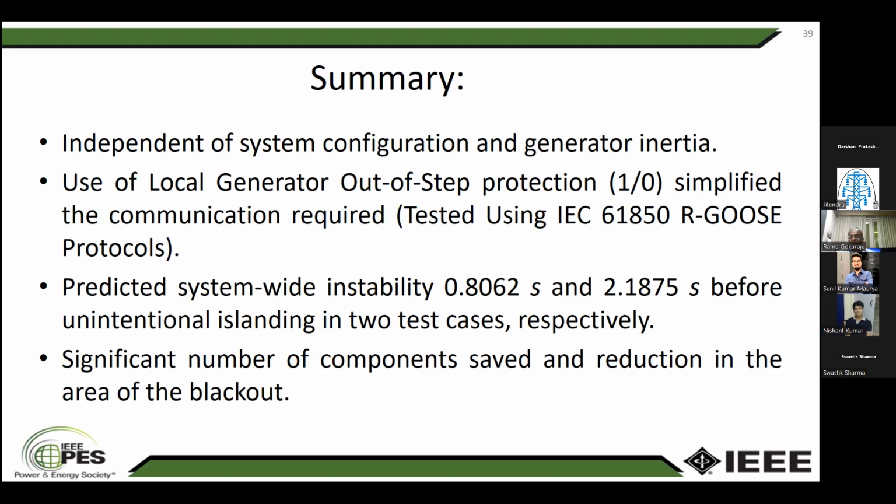We have the M term, so we need the inertia of the generators. And we would need the current operating state of the system, which generators are in service and so on, to find the inertia of the system. And finding the overall inertia of the system accurately is not an easy task.